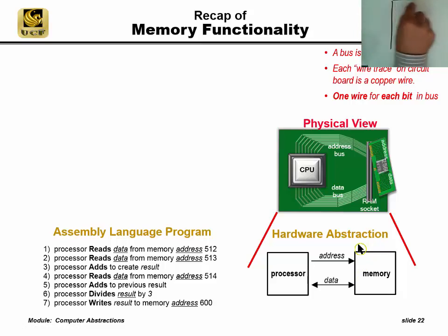So a memory is a linear array of storage cells. The address is written outside the memory. It's not actually stored there, but the address goes from address 0 up to the last address, which is all ones if it's binary. I'll even write a number as a binary number here, base 2. And inside the memory are cells, which are values that are being stored. So this is the depth of the memory, everybody calls it that. And this is the so-called width of the memory.